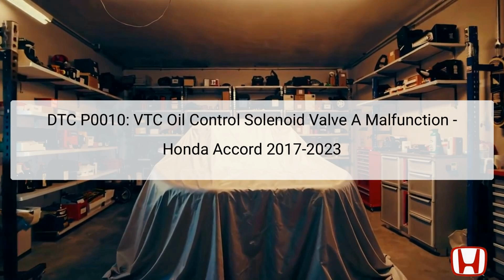DTC P0010 indicates a malfunction related to the VTC oil control solenoid valve A in the Honda Accord models from 2017 to 2023. This solenoid is crucial for regulating the variable timing control VTC system, which optimizes engine performance by adjusting the timing of the intake valves. The valve is typically located near the engine's cylinder head, connected to the engine's oil control system.